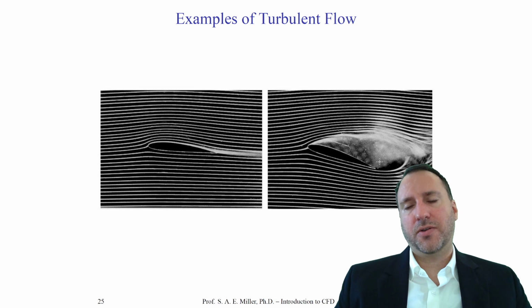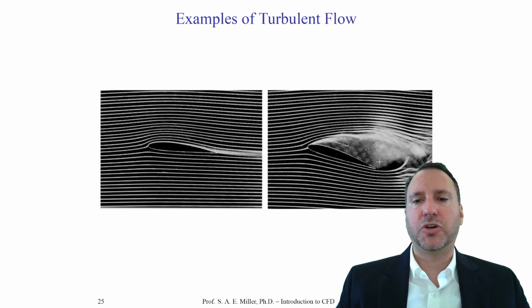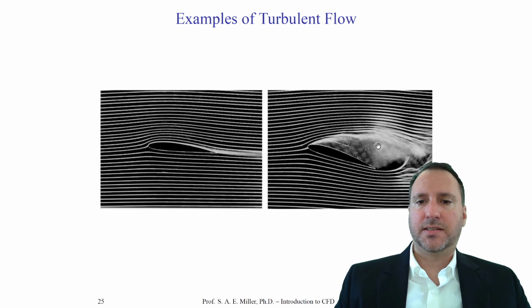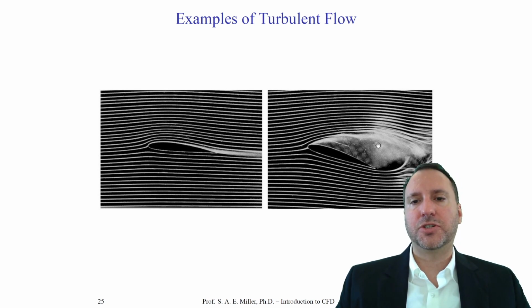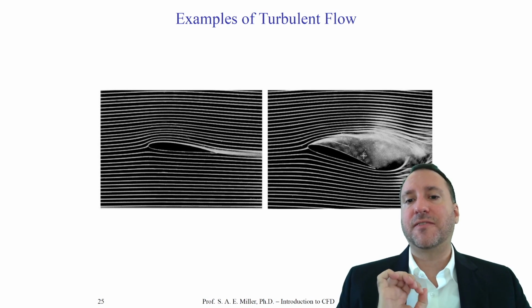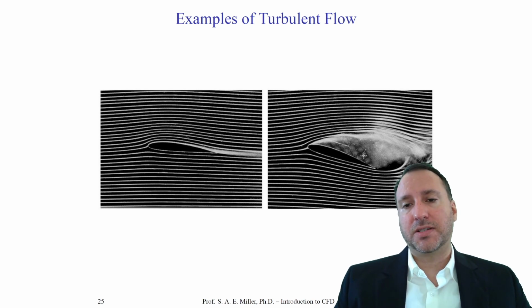You can see the turbulence and the diffusion of the smoke. Recall earlier I noted one physical phenomenon of turbulence is that it is excellent at the dispersion of particulates. In this case, these smoke streams are being dispersed highly effectively in the turbulent regime. That's how you partly know that there's probably a large region of turbulence there, because it's efficiently mixing the smoke particulates.